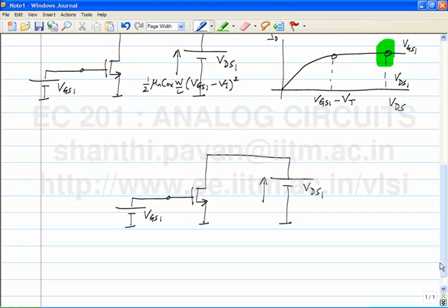Adding the source is basically straightforward. In principle, Rs, Vs. So what is the quiescent voltage across the gate? VGS1. The incremental voltage across the gate? Vs. Very good. And what is the total voltage across the gate? VS plus VGS1. So the total signal between the gate and the source is the quiescent value plus the incremental value. Great. Now I need to add the load.